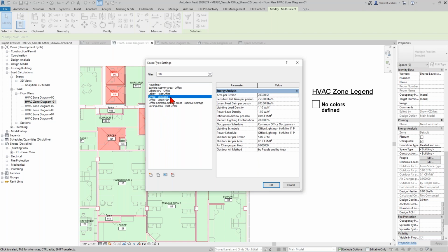I would probably go through and create these space type settings in my template or in the sample building model, so when I cut a new template, they're already there. But have these kind of pre-tuned so that your team, when you're actually designing, they're not needing to go through and manually tweak each one of these. Maybe just do a visual validation.